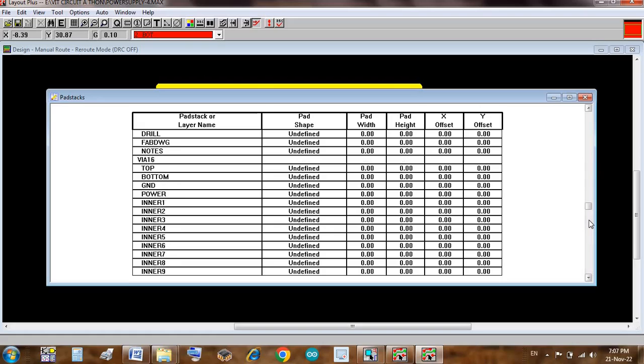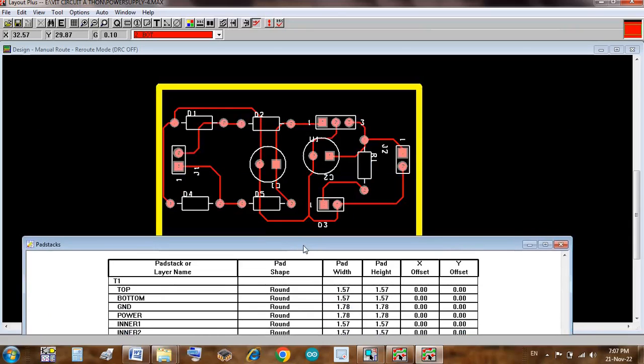There are many things to discuss. Start with VIA or any other tools. You will see in detail at the next advanced level video. Yes, now change the width of the pad. Pad is nothing but what? Sorry. Pad is nothing but the basic footprint impression where we will be placing the component. You have to change this as 2 and solder mask as 2.3.